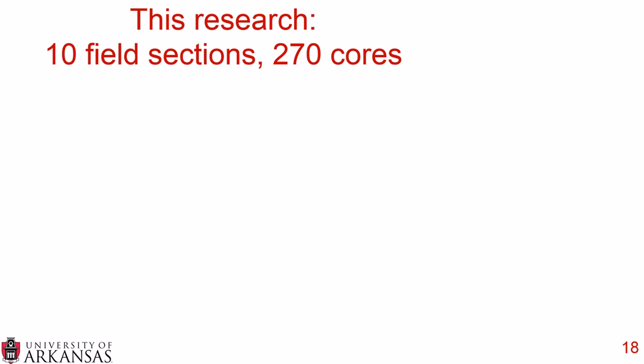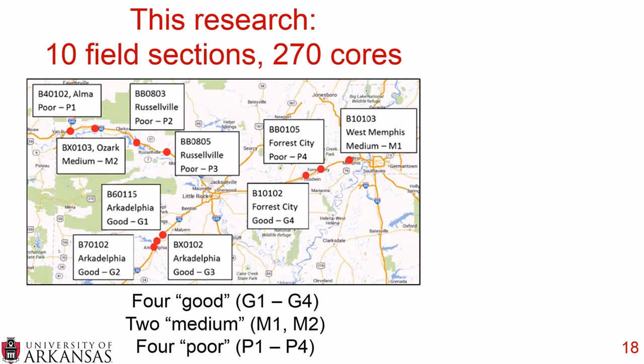So that is a very, very extensive background on master curves, how AASHTO R62 goes about calculating master curves, and then some of our findings from this research project on how we used a little more advanced analysis techniques in order to get higher quality master curves beyond R62. Now we did all this by looking at 10 field sections, and from those 10 field sections, we got a total of 270 cores.